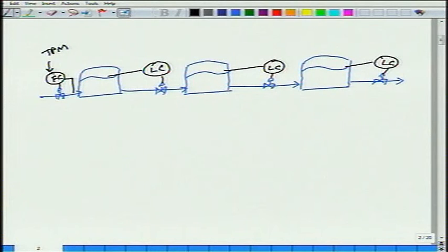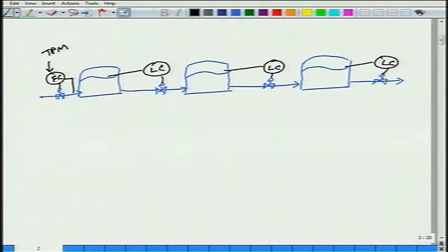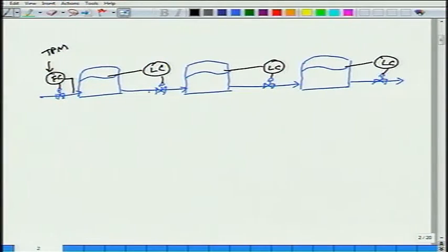Okay. So if you have to maximize production, what would the operator do? Instruction from above is jack up production, produce as much as you can. There is a war coming, produce as much as you can. Okay, fine. So what is the operator going to do? He is going to keep increasing this set point. Can he keep increasing this set point forever? Yes, no. Okay, why not? Level controller will make sure it doesn't overflow. I increase the flow rate, level controller will ensure the outflow also increases.